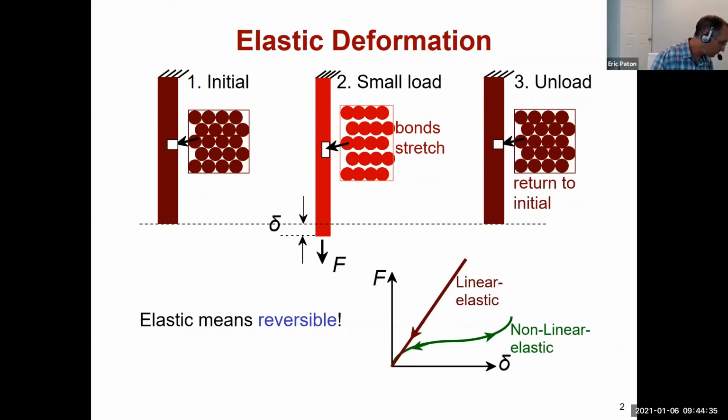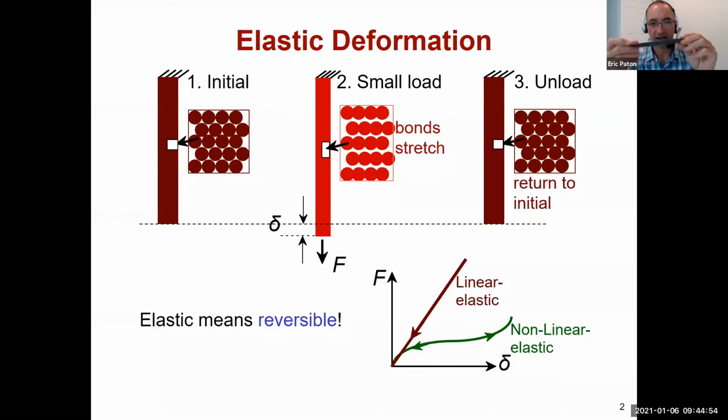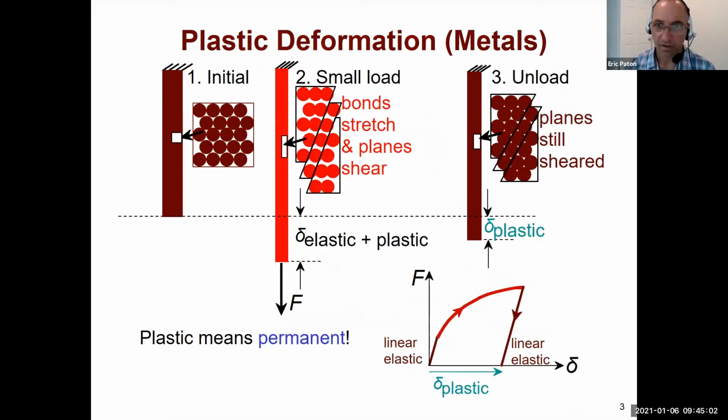So if I were to bend a paper clip, which I'm not sure if I have, here we go. This is a straight edge. With a metal, I can flex it and it's going to bounce back. And that is my elastic region for a metal. If I were to take my ruler and apply even greater force to it, and I really don't want to ruin my ruler, so I'm not going to demonstrate what happens, but you get the point. If I bend this a lot, it's going to turn into a U shape.